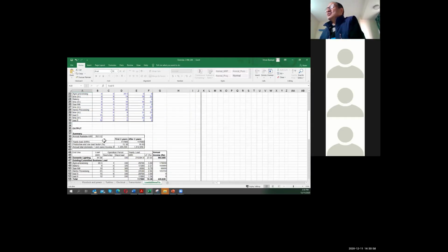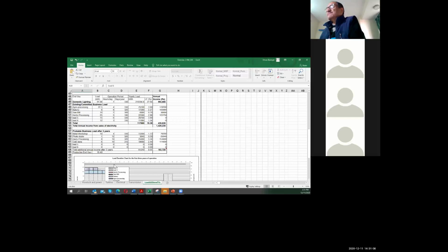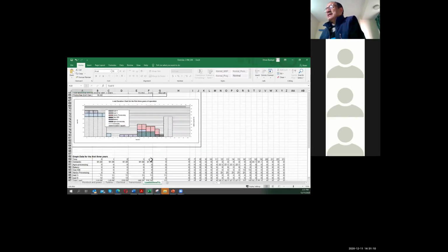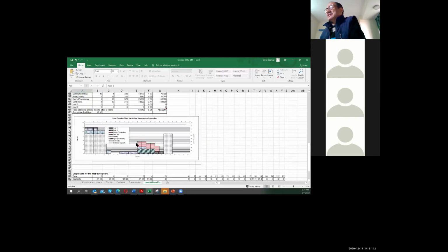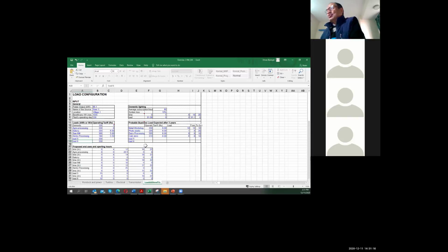Then based on that, you calculate the total kilowatt hour, then based on the supply and demand, you basically get the load curve. Of course, you can play with it and get graphs like this. This is just an example that I wanted to show, but this is the demand assessment, the need assessment in the hydropower project study.